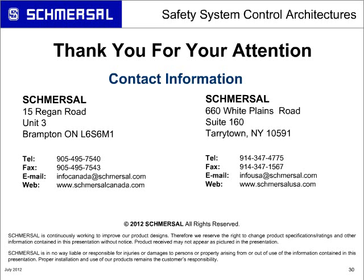So if you're using a motor starter as part of your safety circuit, the relay or the contactor portion of that motor starter has to be mechanically linked. If you're using a separate motor starter from the two mechanically linked contactors for your overall safety circuit, the motor starter can be your normal run-of-the-mill motor starter. It doesn't have to be anything special or mechanically linked, but your two main contactors have to be mechanically linked.